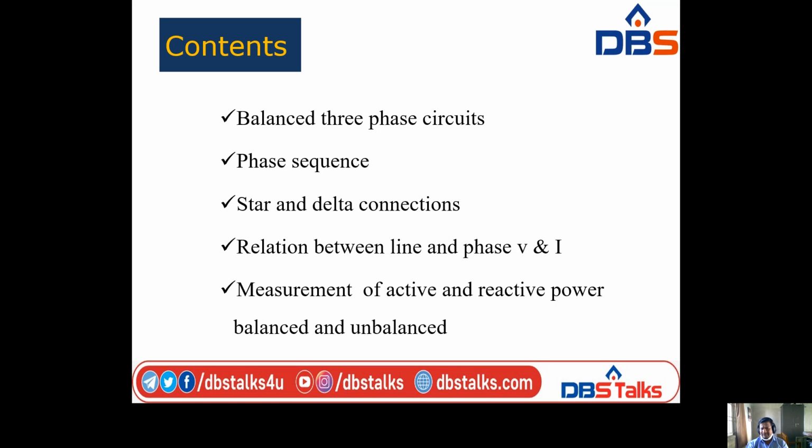Now the last one, measurement of active and reactive power, balanced and unbalanced. How can you measure the active power and reactive power? By using the 2-wattmeter method. So these are the topics.